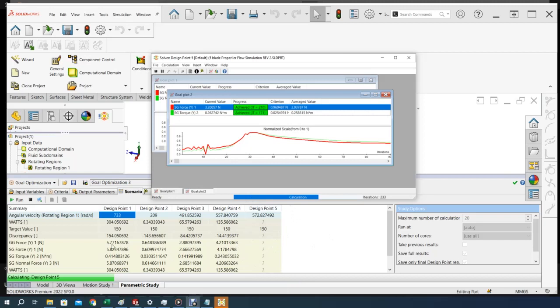But it looks great now. All numbers are positive the way it's supposed to be. The forces, because the wind is coming down, so that's forcing the propeller up. And the force up is the force that we are measuring, as shown here in the global force or the surface force, which are pretty much close to each other in Newton. So let's wait.